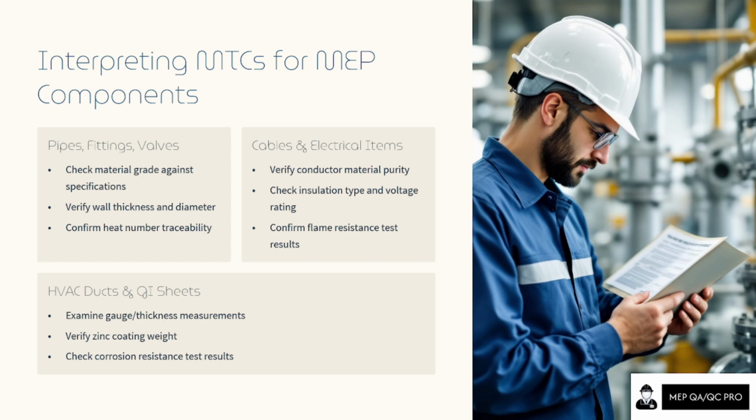Interpreting MTCs for MEP components. We will understand here the material certificate. Basically, from where you are getting this material test certificate for the MEP component, and what checks are required to ensure that the material which arrives at site is as per your own approved technical submittal.